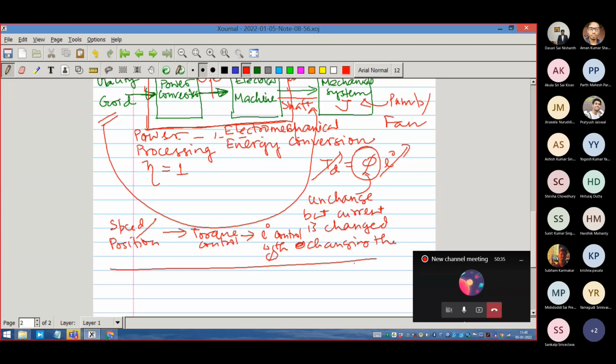So we have to generate a kind of voltage and frequency at the terminal, because it's a voltage source, mostly, voltage or frequency or current or frequency. Sorry, I will come to that. There are two variations. One, just like our Thevenin theorem and Norton theorem, duality is there. You can either do it using a voltage source or using a current source. So when you are using a voltage source, you change voltage and frequency, and if it is a current source, you change current and frequency. These two ways, which are dual, you can eventually handle the torque of the machine. We will understand this. So when we change voltage and frequency, we call it voltage source inverter.